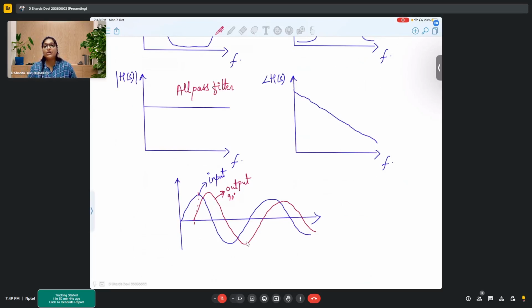A phase shift, if we talk about it from a time perspective, is basically the delay. So it introduces a certain delay in the system. If you have to introduce some delay in the system or you want to introduce some phase shift, so phase shift and delay are analogous to each other, that is done by the all-pass filter. So from here, we can clearly observe that from the Bode plot, we can comment on the stability by looking at its crossover frequency and phase analysis. We can also comment on the functionality of the circuit, like what is the function of that circuit.